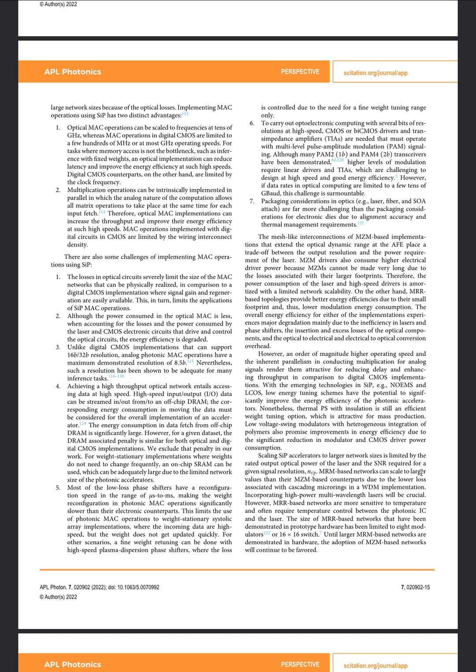Both Mach-Zehnder modulators and microring resonators experience major degradation to overall energy efficiencies. This is because of inefficiency and losses in lasers and phase shifters, insertion and excessive losses of the optical components, and the optical to electrical and electrical to optical conversion overhead.